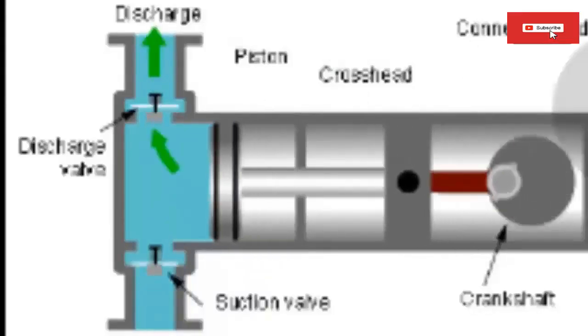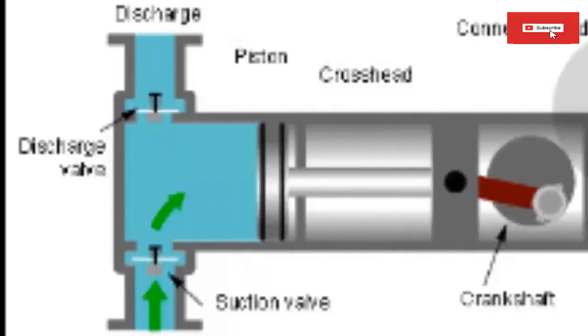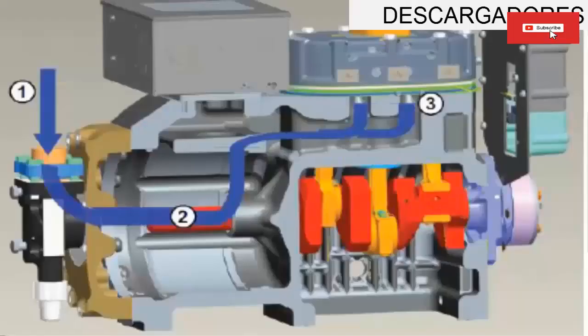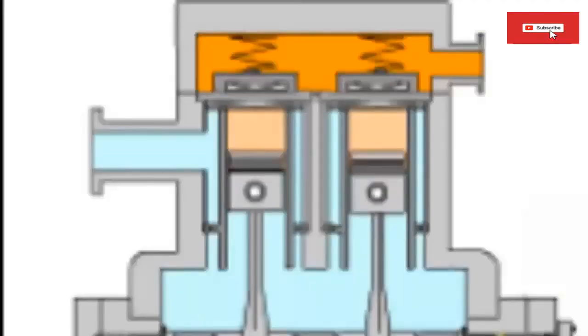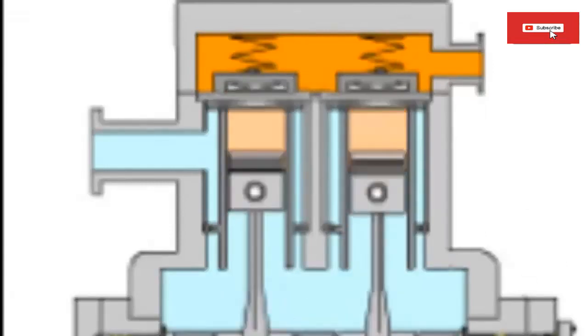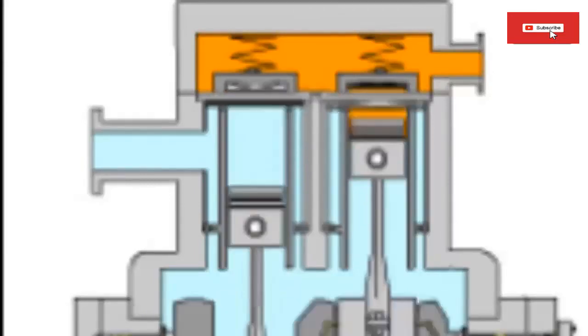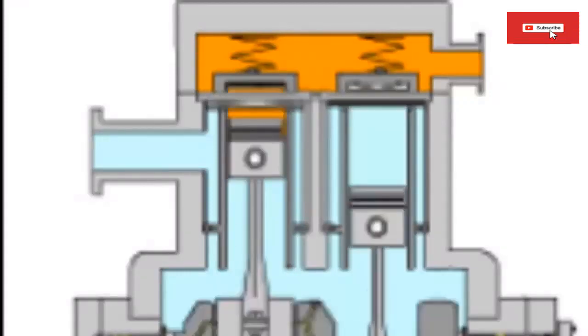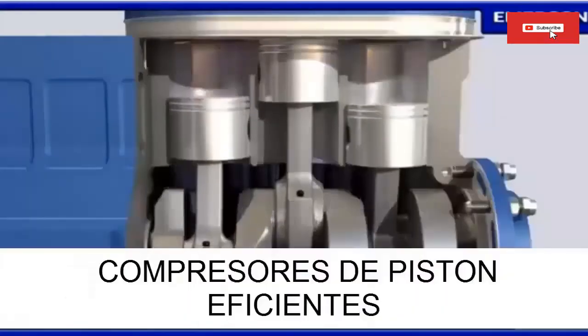Currently, capacity regulation mechanisms in reciprocating compressors are well known, using unloaders and the digital regulation method. Both methods are very similar, because they seek to eliminate the suction of coolant in the pistons that are not needed. The main difference between these two methods is that the regulation by unloaders works by capacity ranges, while the digital method works almost at the same rate as the need for cooling. Next, we will explain these two methods in more detail.